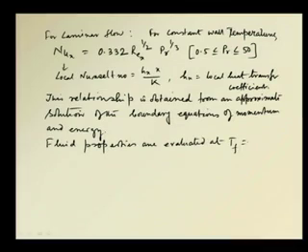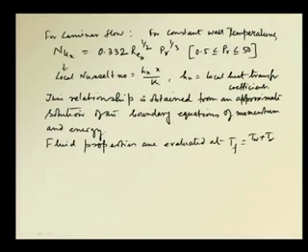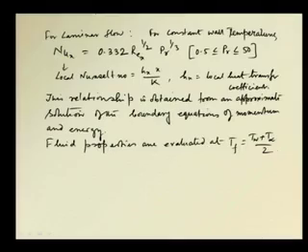We have already discussed this, and film temperature is, we know, wall temperature plus bulk temperature. Here the bulk temperature is nothing but the free stream temperature. So, it is TW plus T infinity by 2. So, it is the arithmetic average of wall temperature and free stream temperature. So, TW is the wall temperature and T infinity is the free stream temperature. At that temperature, we have to evaluate all the fluid properties to get the values of Reynolds number, Prandtl number, and also thermal conductivity, to get the values of heat transfer coefficient.